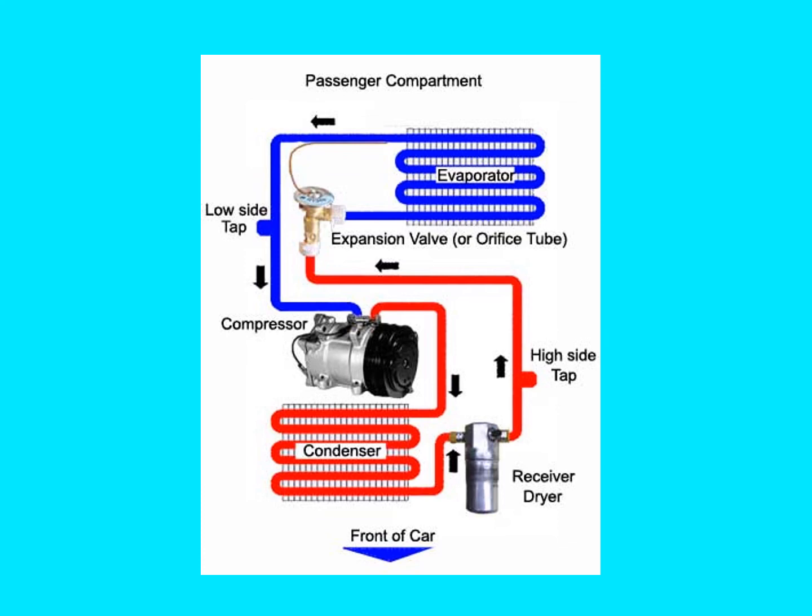So the refrigerant flowing to the condenser is going to be a high temperature, high pressure vapor. Okay, the compressor can't operate on liquid refrigerant, so just because of that, it's going to be vapor coming into it and vapor leaving it. So the vapor goes into the condenser.